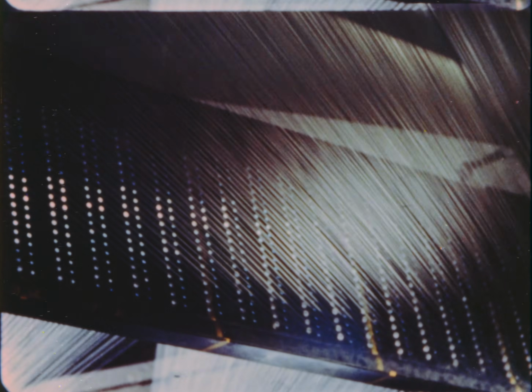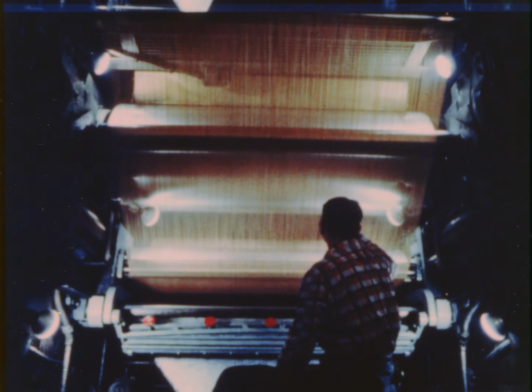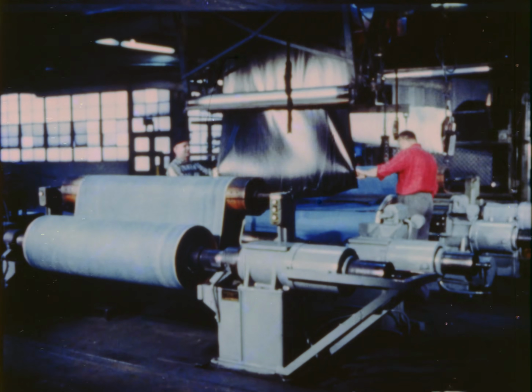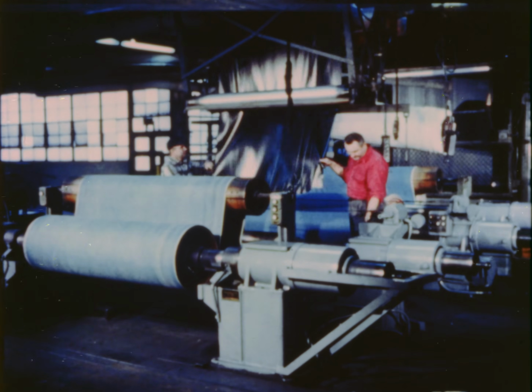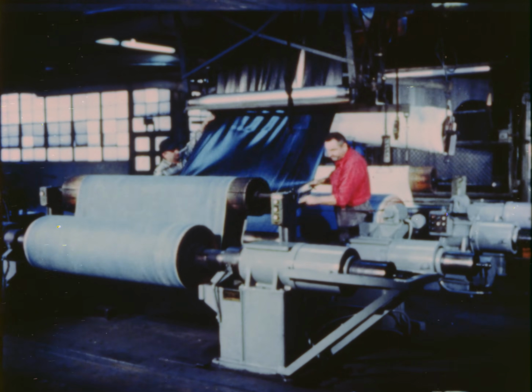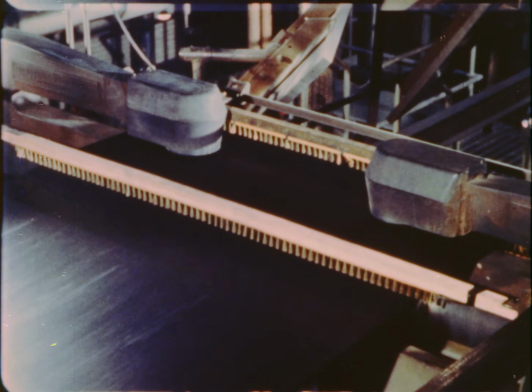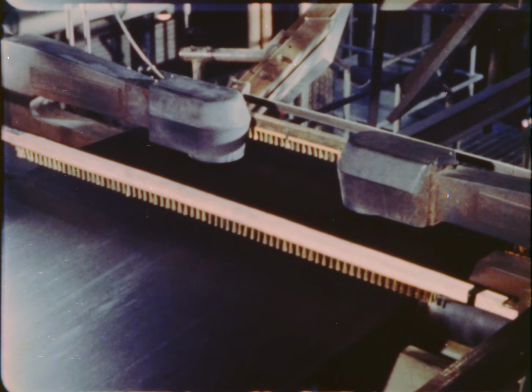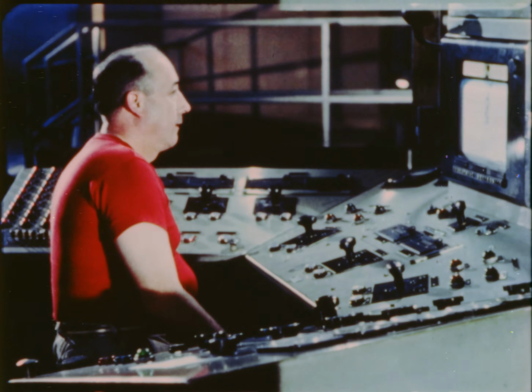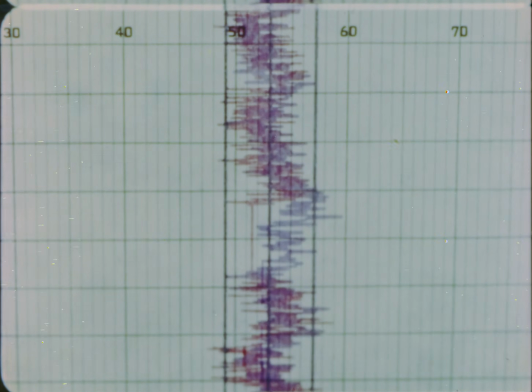At a tire company, nylon cord is being carried into a calendar. Here it will be coated with rubber of uniform density to form sheets of tire ply material. As the sheets leave the calendar, they are constantly measured by two gauges set at positions of average sheet thickness. The gauge circuits actuate a continuous recording chart calibrated in pounds per square yard and automatically adjust the gaps between the rollers which control the amount of rubber fed.